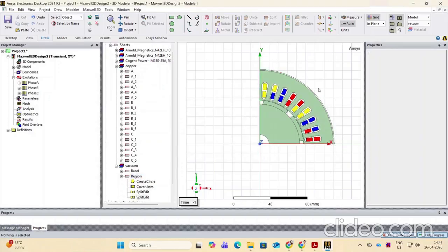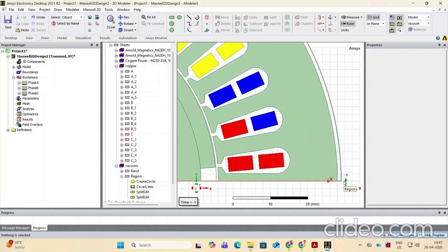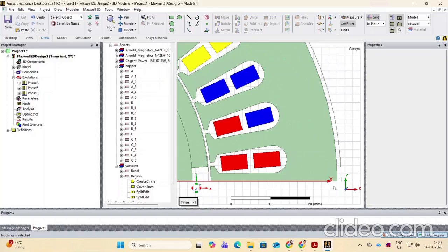Okay. Now, as it is a part model, we have to define that this is not a complete part and it has continuity below the x-axis and on the left hand side also of the y-axis. To do that, we have to first understand what is the type of this continuity. Okay, so we'll see it. First, you have to press E from your keyboard.